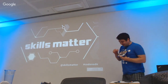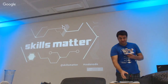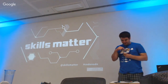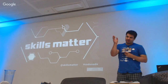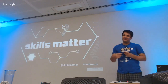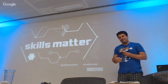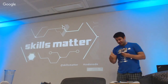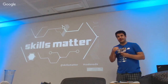So the main thing is that it's all MQTT messaging between the two. The way that it finds this particular Raspberry Pi running the game server is when this powers up and joins the Wi-Fi network, it sends a multicast out on a particular address that says Marco, and the server responds Polo, and at that point it knows its IP address. So it then does an MQTT connection to that server, and at that point it can start sending messages to the game server, which then responds back, and this then knows what's going on in the game at that particular time.